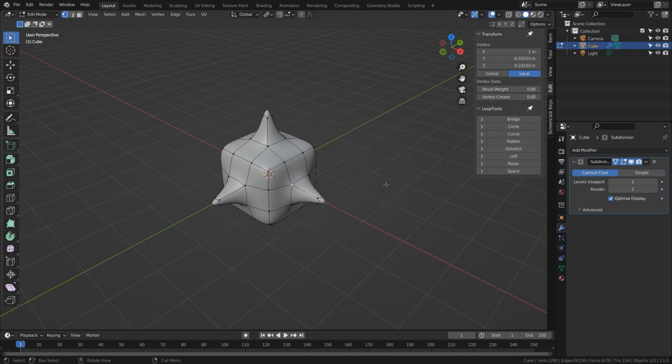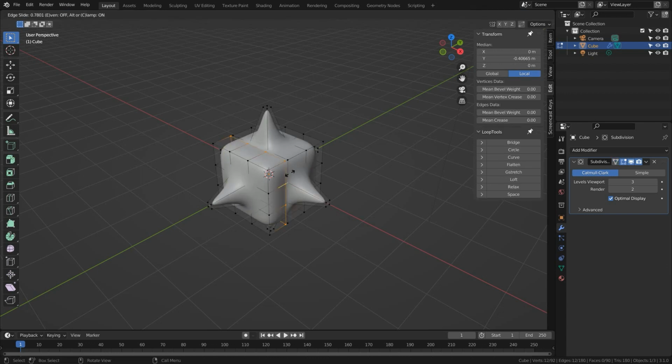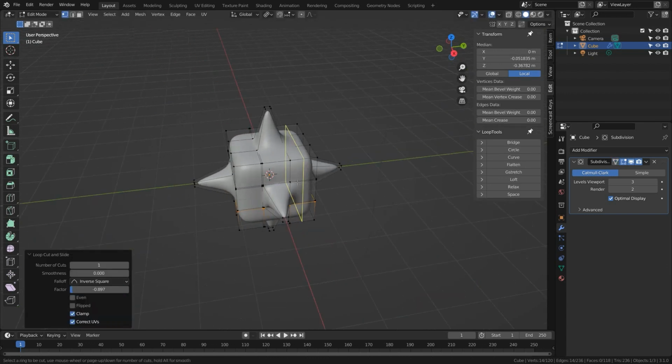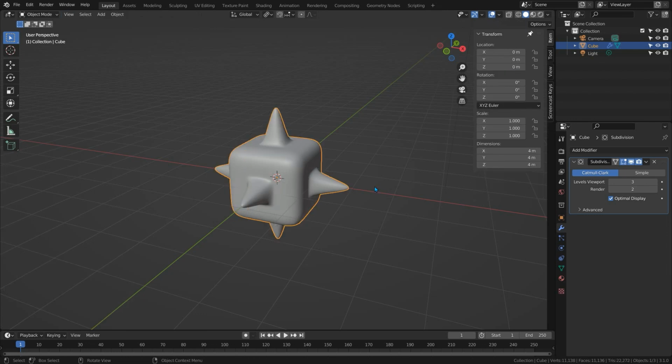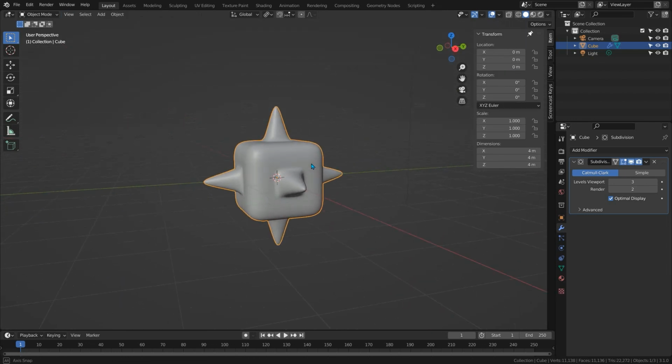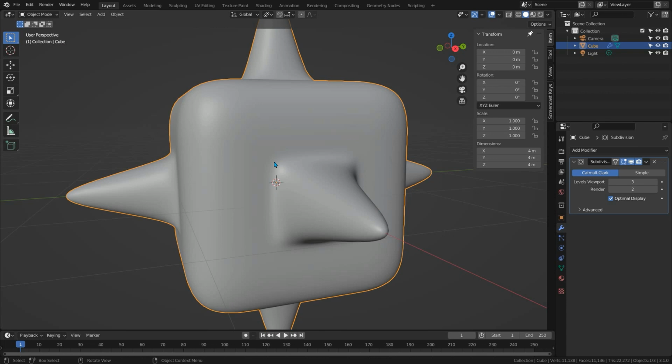The only problem comes if we want to change the softness of this connection without changing the shape above it, and that happens all the time. We now have to do it by adding tightening loops, which go all around the mesh, and they're all affecting each other, which in this case is actually quite beneficial, but generally it won't be. Now if we look at it, the connection looks fine. It's perhaps a little square at the edges, but that could be the shape you want.